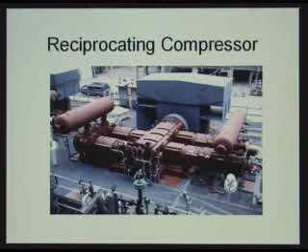Production flow is the gas comes into the pulsation damper on the top, flows down through the cylinders and discharges out the bottom. That way, if there's any liquids that happen to form, they have a tendency to drive themselves out rather than build up in the bottom tank until the level reaches the cylinder and causes a hydraulic lockup of the compressor.